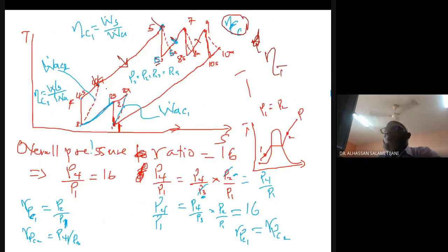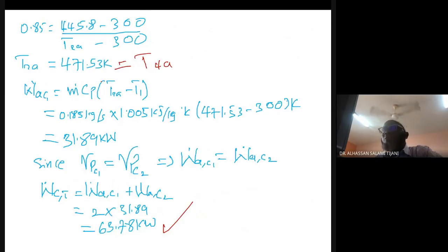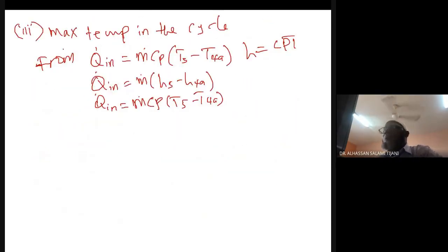You see, the temperature at this state is the same as the temperature exit because of what? They have the same compression ratio. If they are the same compression ratio, the temperature at the inlet over here, state 1, will be the same as the temperature at the inlet at state 3. Similarly, the exit temperatures are going to remain the same for both compressors. Okay, so therefore we conclude that T2A is the same as T4A. All right. So from here, we will have